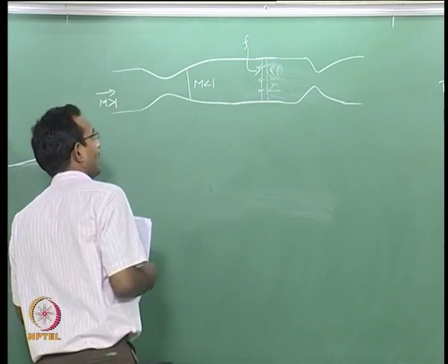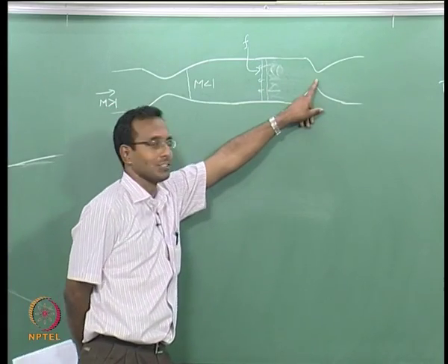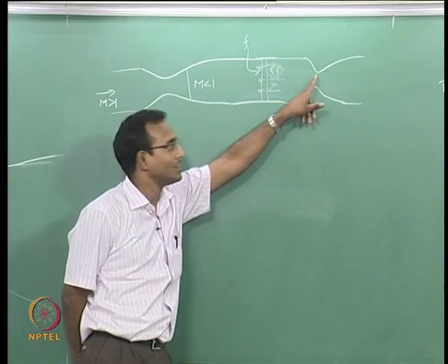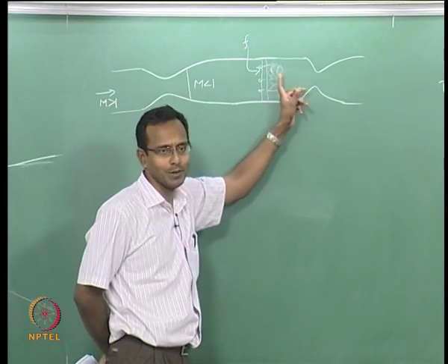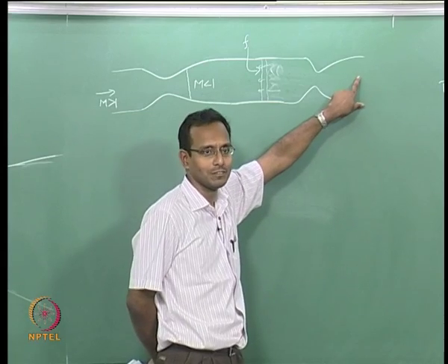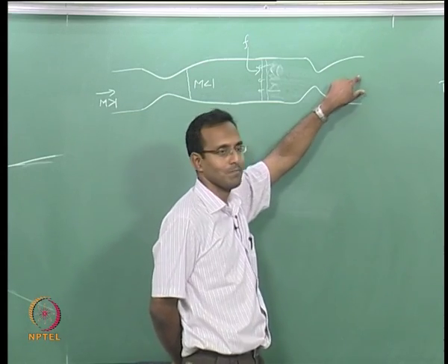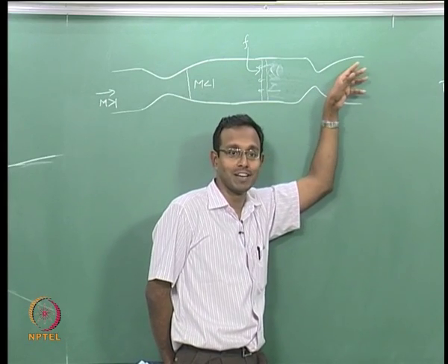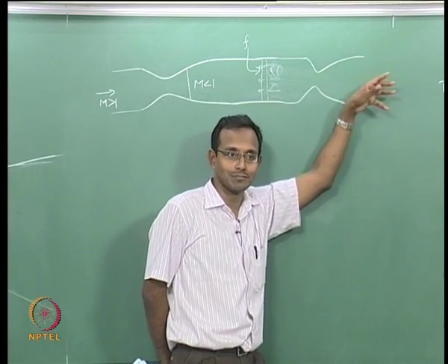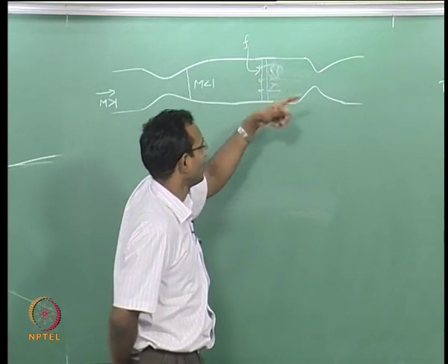Okay. Now what happens if I choke this? If I choke this point and I add a little more heat, of course it has to be choked for me to get back to supersonic Mach numbers here, otherwise I am taking the flow incoming supersonic and sending out subsonic, which is a waste and it is going to be a drag. We want it to be a thrust, okay.